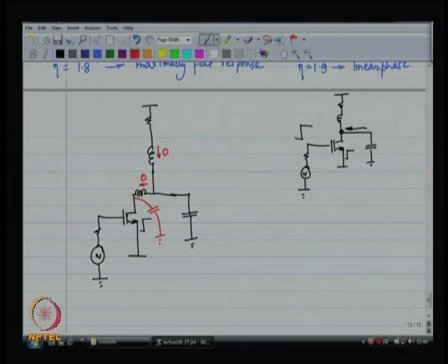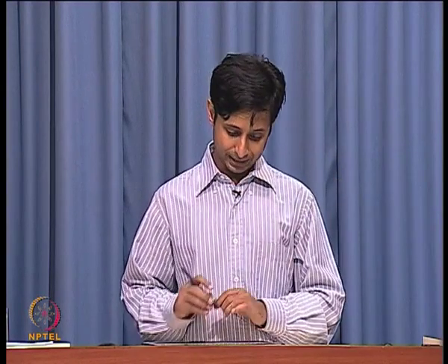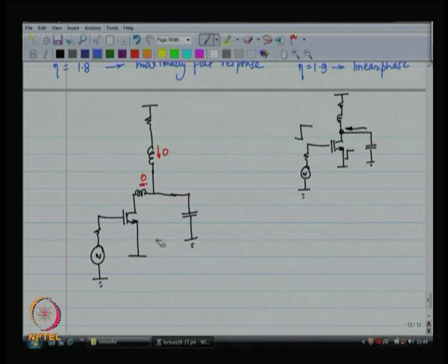So, the inductors are not going to allow any current to flow through them, which means that the capacitor, which was pre-charged to the power supply, this parasitic capacitor, is going to discharge. So, first the parasitic capacitor discharges, right. Now, the parasitic capacitors have discharged. Now, the inductors do not have a choice, all the current now has to come through the inductor, okay. And now, the same story starts again.